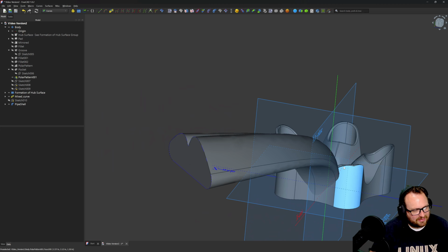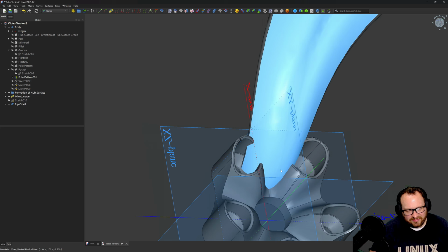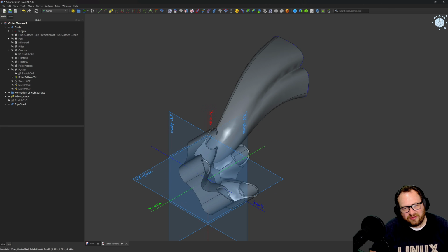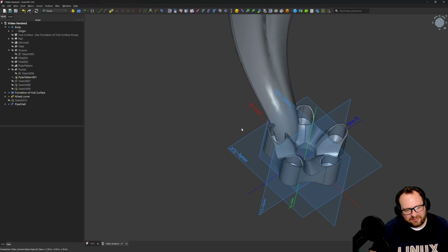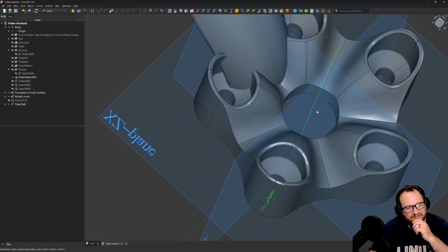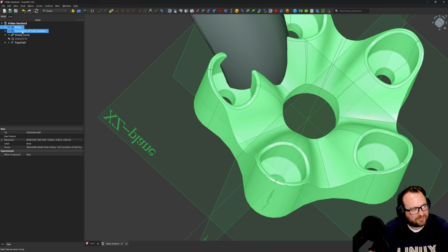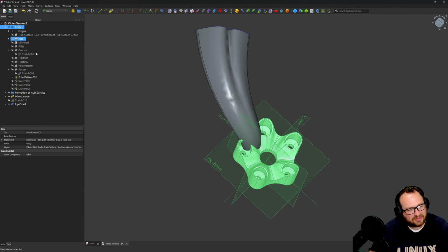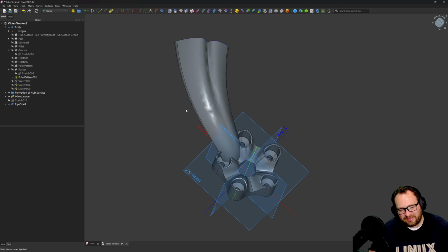And just like that, we have a very solid. I love this spoke. You can see that it is going into where our lug nuts are. So let's tune that so that we can have some nice geometry and not have to worry about it. So again, by the way, this pipe shell was made in the surface workbench. So if I collapse my part design body, we can see that the surface exists outside of my part design body. And we're going to just do a Boolean as we've done before with references in the tree.